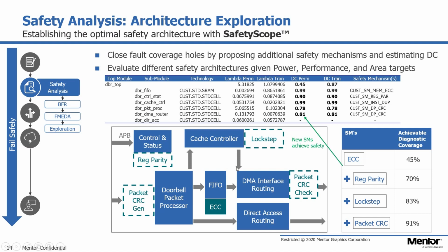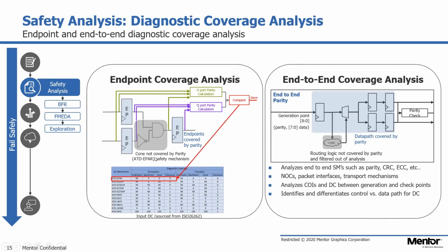And so I can just, by changing this configuration file, applying additional mechanisms or removing mechanisms up to my considerations and estimations, directly see the impact of what would happen if I added these kinds of safety mechanisms to my design. And then, of course, this will also have an impact on my FIT rates. And then I can, at the end of the day, I jumped ahead, I can run this exploration.